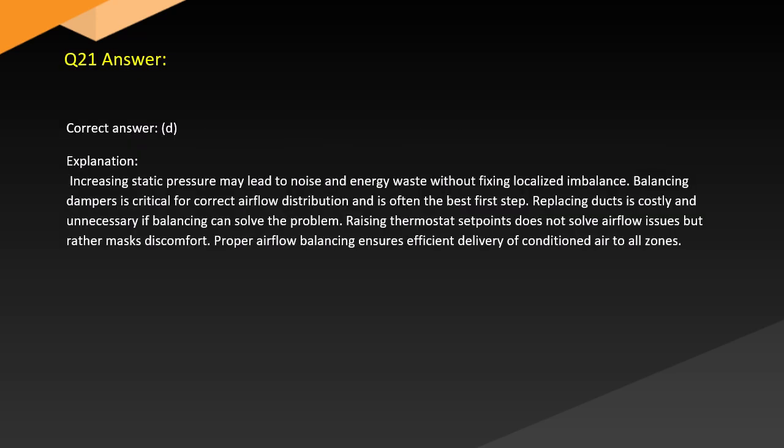Answer. Correct answer: D. Explanation. Increasing static pressure may lead to noise and energy waste without fixing localized imbalance. Balancing dampers is critical for correct airflow distribution and is often the best first step. Replacing ducts is costly and unnecessary if balancing can solve the problem. Raising thermostat set points does not solve airflow issues but rather masks discomfort. Proper airflow balancing ensures efficient delivery of conditioned air.